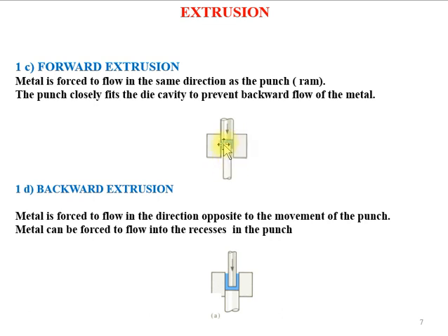So we place the raw material above this mandrel inside the die, and we make the punch move from up to down. The size of the punch will be as close as the size of the opening that we have on the die. So when the punch hits the raw material, the billet,